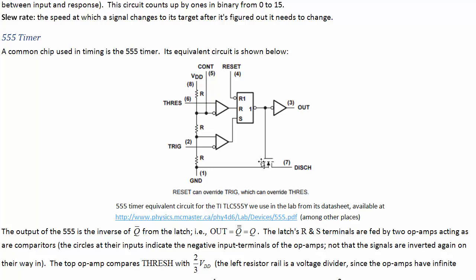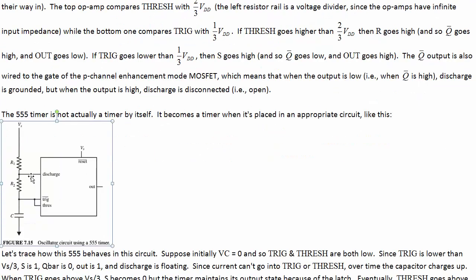This thing, which we didn't talk about yet, is an N-channel MOSFET. You can tell it's N-channel because the arrow is pointing towards the direction the majority charge carriers would go if we put a positive charge there. So that means they're negative. So the majority charge, the things that we would fill up the channel with, are N. So if we put the set bit on, then this is a 0, and so this is not turned on, and discharge is not connected. Okay, so discharge is just sort of floating. It's not connected to ground. So we can ignore this pin.